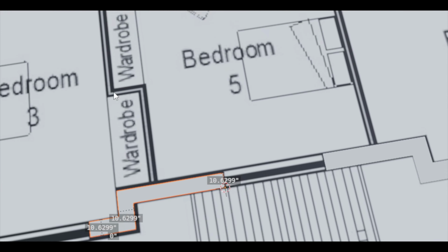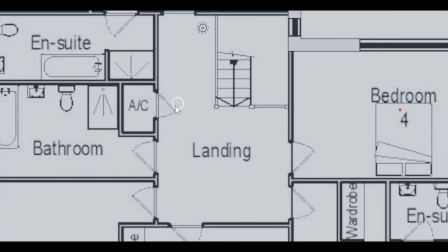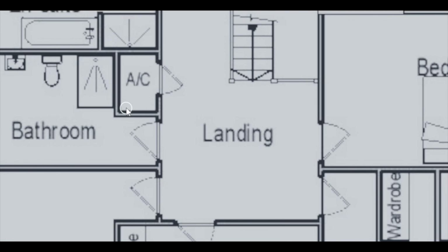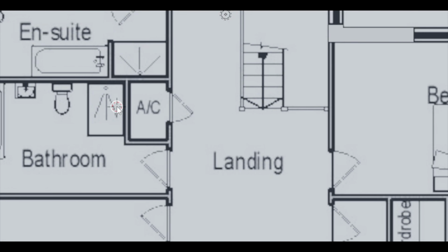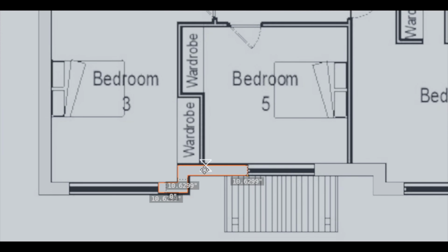And now when we come inside, we might use the middle mouse button and Alt to snap it to the top view, and then we'll press Shift plus right mouse button to move our cursor wherever we want to start. So let's say we're going to start here at the front door with this interior wall.